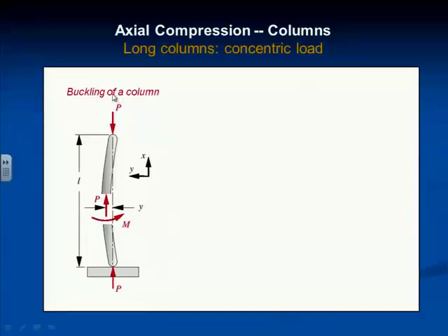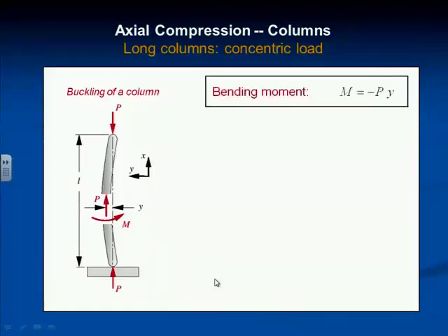By the way, all these formulas are based on the assumption that the loads are concentric, not offset, right? Because clearly if I start out holding this on the edge of the table like that, and I push on this side over here, I've already got a bending moment, right? There's a couple there. So I'm sort of goosing it. I'm going to go quicker to failure that way than if I'm right in line, right? So these formulas are assuming you're perfectly in line. I'm not going to get to it in the lecture, but in the book I give you the approach when you know that they're not in line, called the secant formula. That's still a third approach that I'm not going to cover here today.